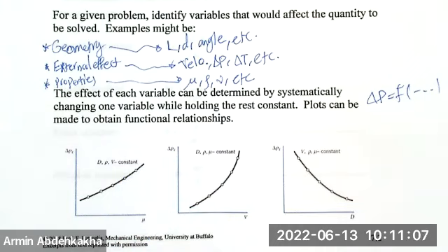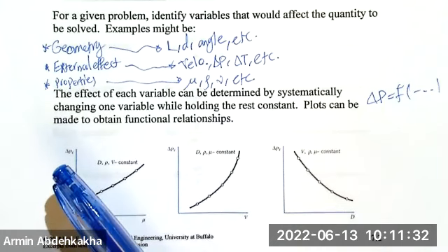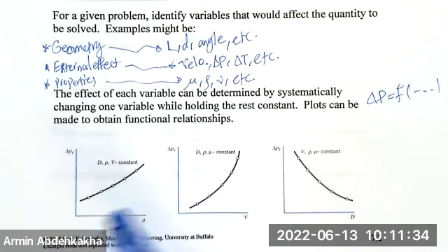That's why Reynolds is a non-dimensional parameter that will help you compare different models, right? And that's why it works for finding the transition between laminar and turbulent, and whether you are in turbulent flow or laminar flow.